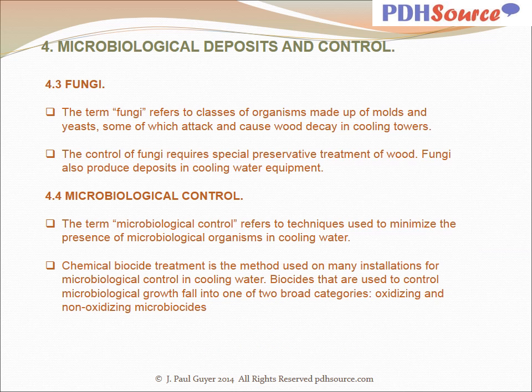The term fungi refers to classes of organisms made up of molds and yeasts, some of which attack and cause wood decay in cooling towers. The control of fungi requires special preservative treatment of wood. Fungi also produce deposits in cooling water equipment. The term microbiological control refers to techniques used to minimize the presence of microbiological organisms in cooling water.